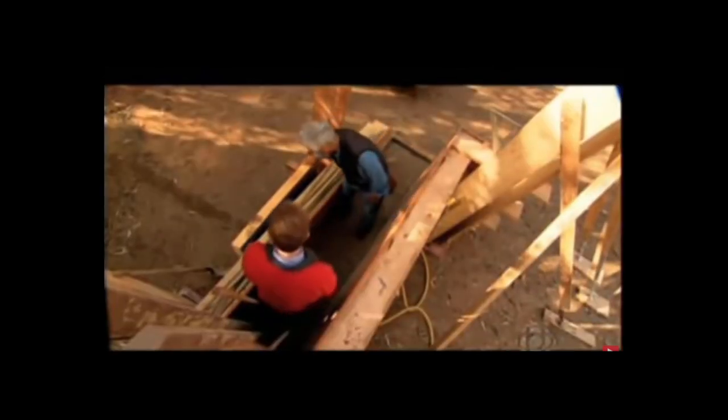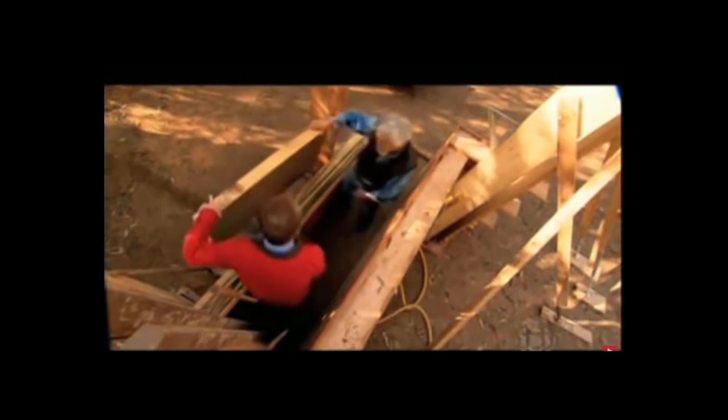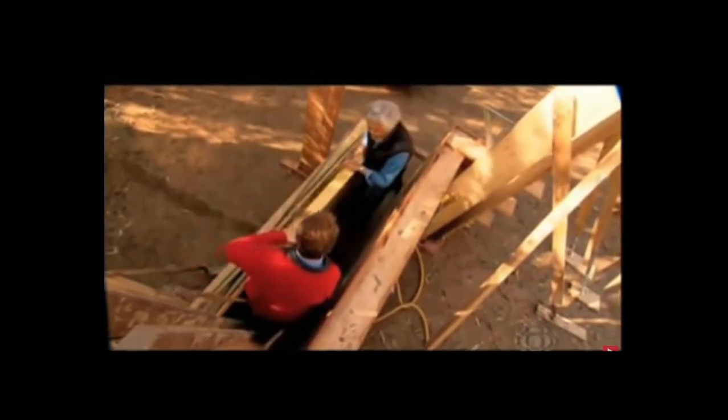Some things haven't changed. Soil still forms the basis for making rammed earth walls. We're using the material that comes from beneath the topsoil, and we're careful about our soil selection, and then we compact that. Okay, we're standing in the formwork, and we're going to put some foam in. And that's the insulation. That's exactly right, yeah. Okay. Mira Krajinoff has adapted the process by insulating and strengthening the walls. And then we take some steel.